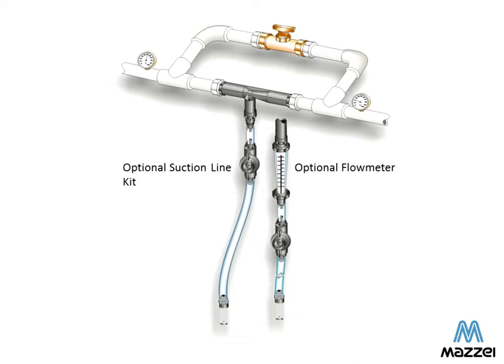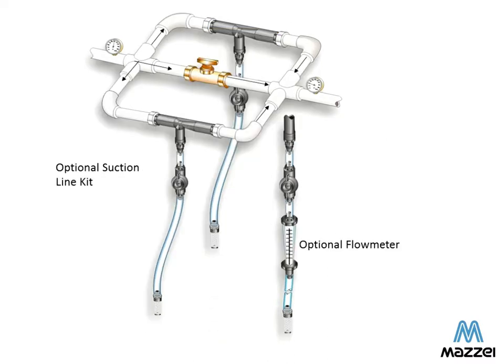You just close that pressure reducing valve down until you initiate suction, until you have sufficient pressure differential to initiate suction. And because the injector and the pressure reducing device are in parallel, they see the same pressures at their inlet and outlet. You can do this with multiple injectors. Same principle applies. Close the valve down until you have sufficient pressure differential. Both of those injectors will see the same pressure differential and will initiate suction.